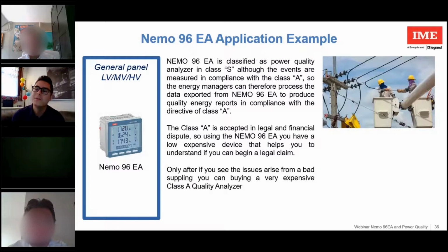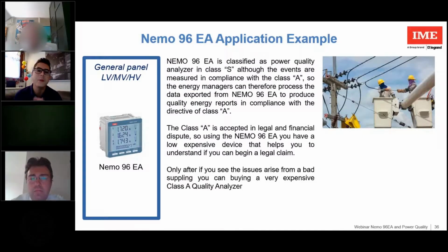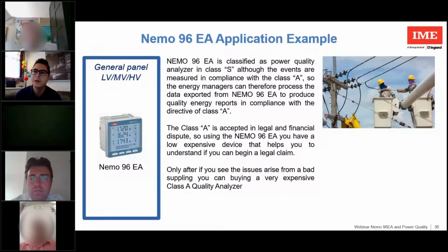Really, I never found an application to put a threshold on THD, because as I say, it is a problem that you have or you don't have. If a problem occurs in your system, it is more an alarm produced by a differential relay, not by a multifunction meter or a quality analyzer. Because in order to reduce the THD, it's not a value that increases temporarily.